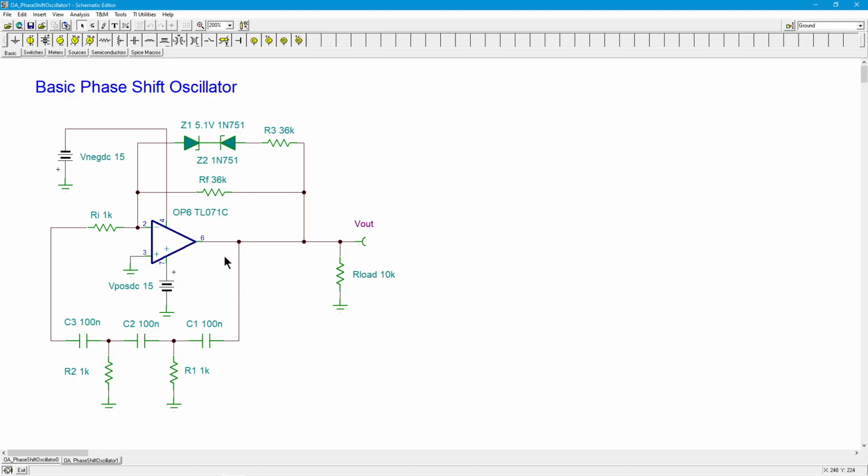All right, so this is probably, for the most part, going to be designed empirically. We know a rule of thumb, like I'm not going to put a 15 volt Zener up here because I only have a 15 volt power supply. But you're probably going to just play with these. If you're in lab, monkeying around, you can put some values in here, try different values for R3, and again, depending on tolerances and whatnot, you might find a slightly better value for your RF. But basically, this thing should settle in on this one frequency. So we, by formula, predicted this would be like 650 hertz.